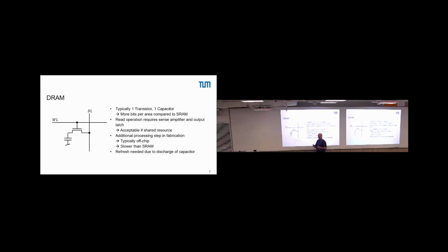So they start recombining. Now what happens is that the sense amplifier amplifies that wire up to VDD again, because we have this tiny peak. So the sense amp causes VDD again. This VDD applied by the sense amplifier causes, since the switch is still closed, that we again store here the value of 1, right?